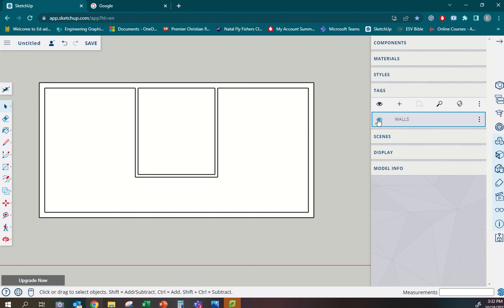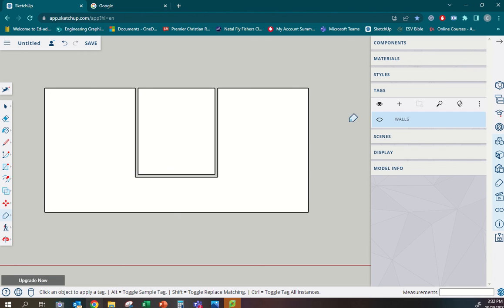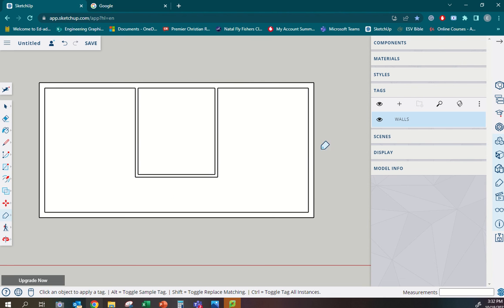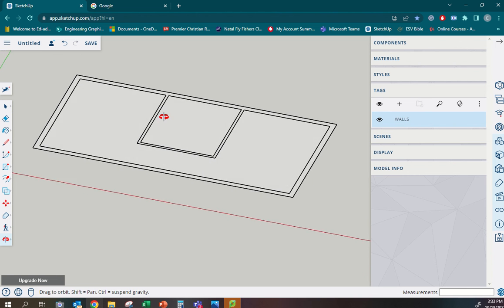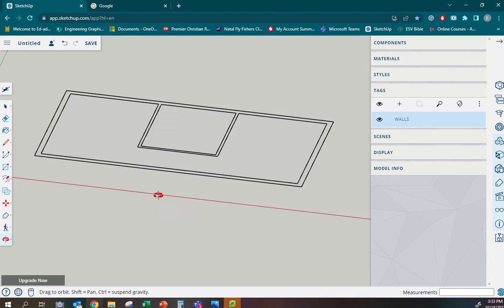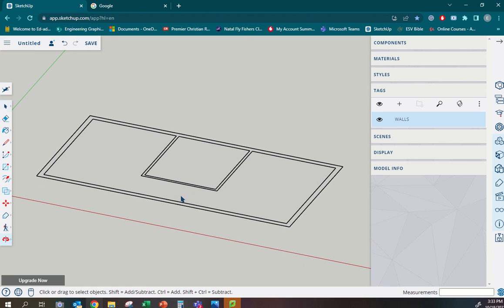Right, so what I should be able to do here is hide that wall now. There it is. Hide it, show it, and hide it. And what you're really left with would be whatever the concrete surface bed would be. So in order to work on that now, because what we need to do with this wall is extrude it up a certain height, I'm going to double click on the cursor command. I'm going to use the toggle key on my mouse, hold it down, and orbit around my object. It's just the middle toggle button on your mouse, and I'm going to hold shift and drag it down a little bit.